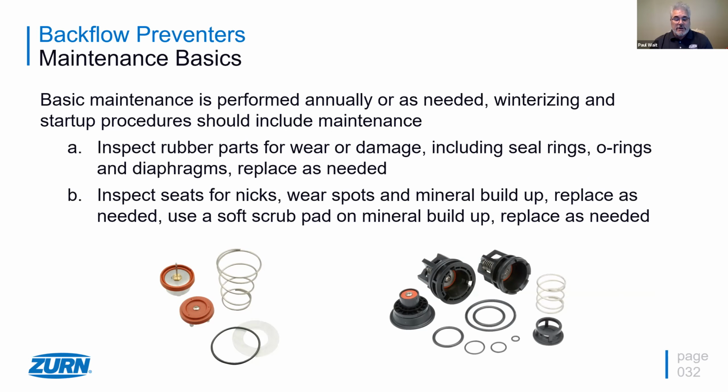Yeah, so it's a good question too. So the question here is basically the 45-degree open close, half open, half close on winterization for ball valves. And yes, what happens is there's a little socket or little pocket behind the ball and the cup, which is the plastic cup, the Teflon cup inside the ball valves, and water can get back behind that.